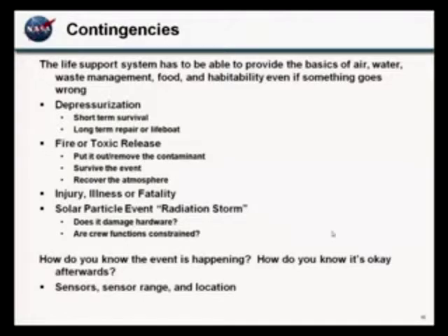Depressurization is one of the first ones. You have both short-term and long-term issues here. Short-term issue, we typically talk about feed the leak. If there's a small hole in the vehicle, you need to be pumping air in as fast as the air is going out in order to maintain the pressure so that the crew doesn't pass out or die quickly. You need them to be able to get into spacesuits, get into a breathing mask, get into something so that they can make decisions and make some kind of intervention to hopefully stop the leak.